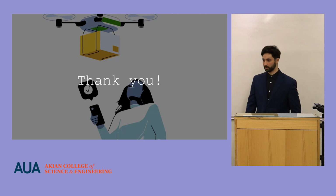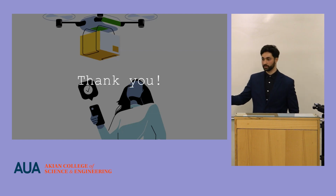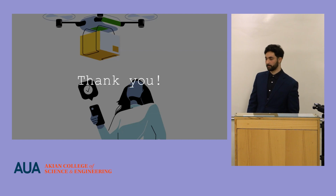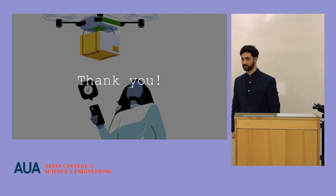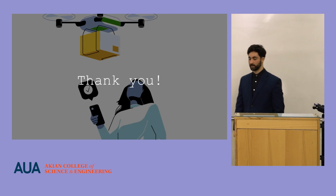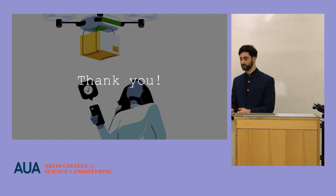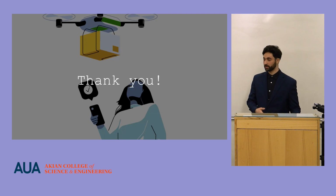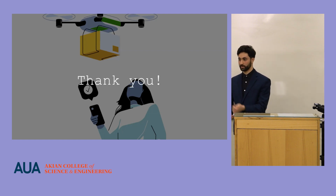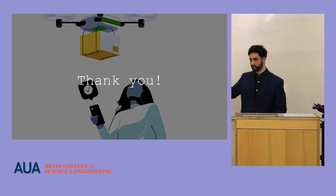Yeah, I have the code for that. I already showed how it was working with the camera. That's the computer vision part with OpenCV. Okay, that part I understand. But whether there is a connection with the autopilot to move it to the center. Yeah, there is. I have the code, but I didn't have a safe environment to test the drone to move on its own. But yes, it would work the way you're saying. It would detect the Aruco, and it would move left, right, up, down until it places it exactly in the middle, slowly, gradually.